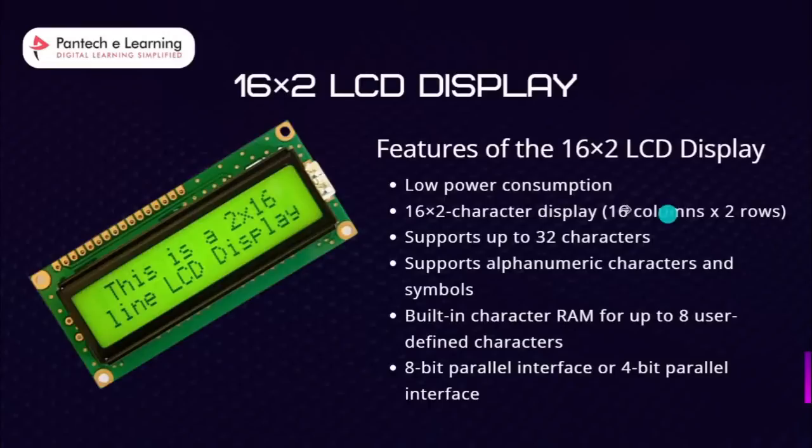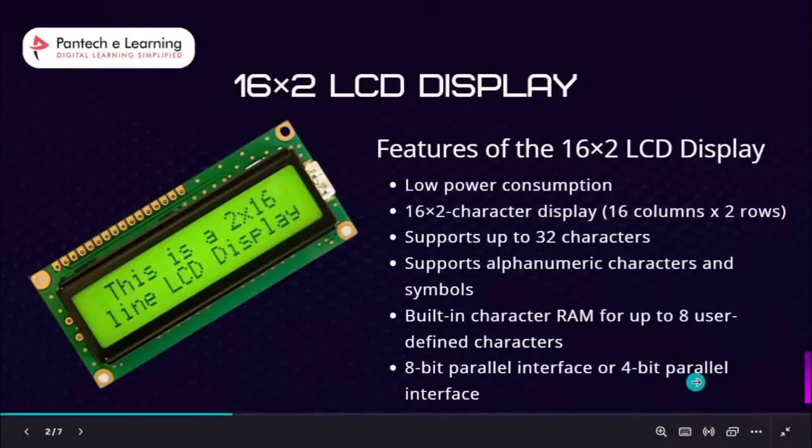These are the features of the 16 x 2 LCD display: low power consumption, 16 x 2 character display, supports up to 32 characters, supports alphanumeric characters and symbols, built-in character RAM for up to 8 user-defined characters, and an 8-bit parallel interface or 4-bit parallel interface.